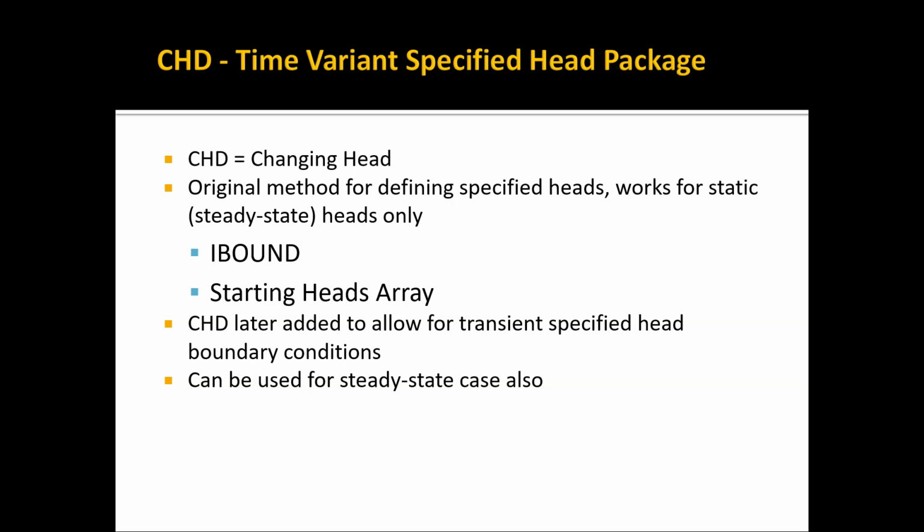And there's no barrier to flow. There are no sediments, or the sediments have about the same hydraulic conductivity as the aquifer itself. And so I'll try to remember to do this in one of our classroom exercises, but if you take the general head boundary condition and you give it a really large conductance, which would be a very large value of hydraulic conductivity, you get basically the same results as you get with a specified head boundary condition.